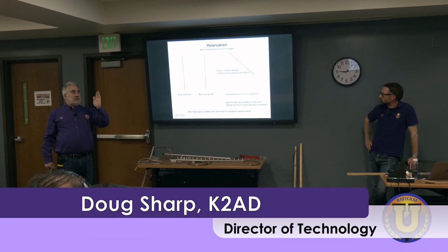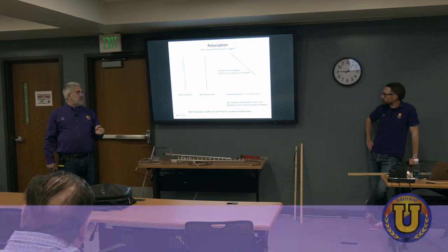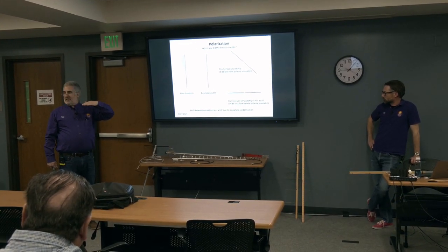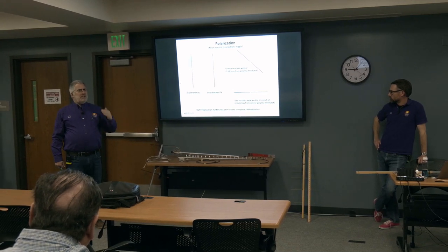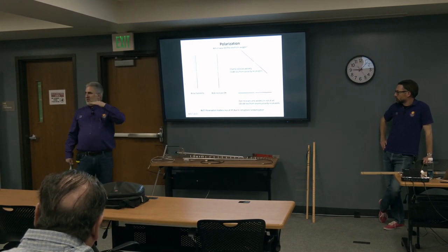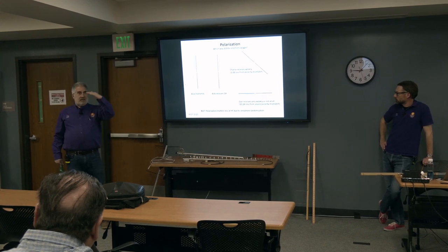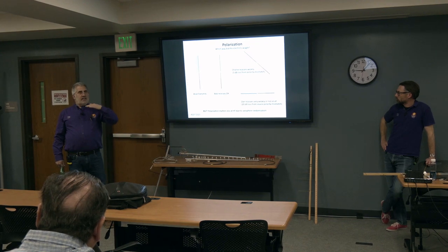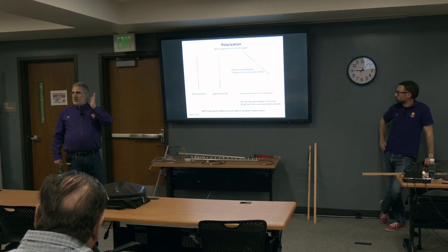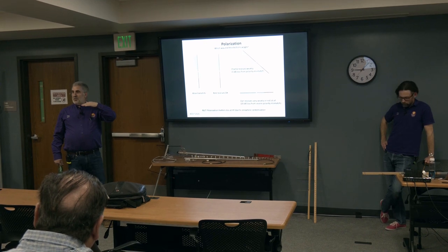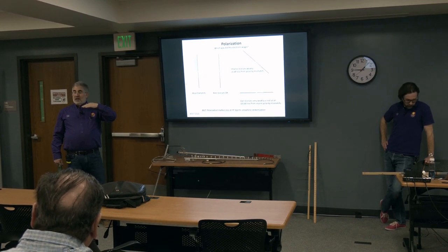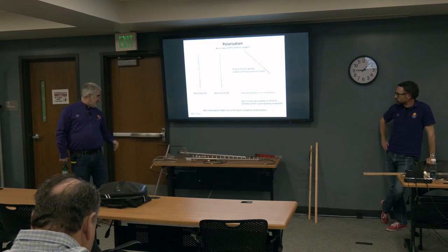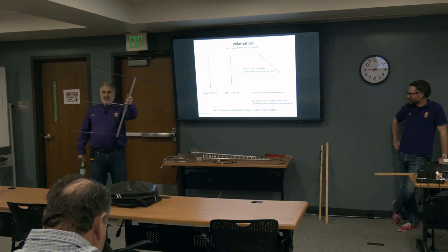a FM signal, we typically put vertical polarization. Single sideband tends to be horizontal polarization on VHF bands. Why did we do that? Why do we run horizontal? On single sideband and CW where you're running weaker modes or even digital, man-made noise tends to be vertically polarized. And we get lower noise horizontal. So why did we go to vertical in our car? Because it's really tough to mount a horizontally polarized antenna. Do you want this sticking out the top of your car?